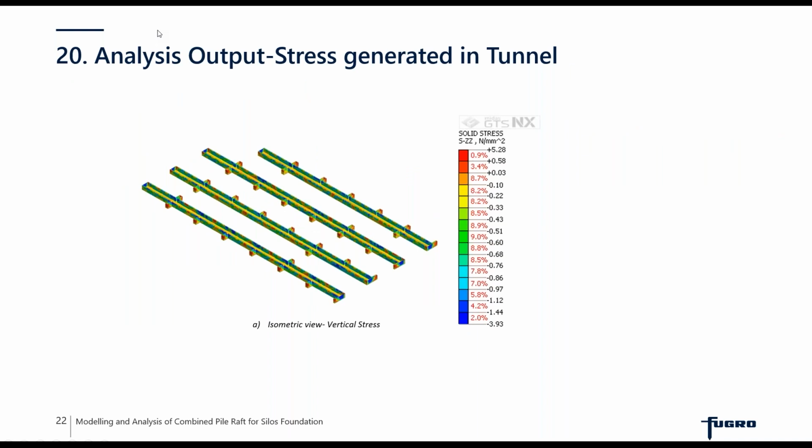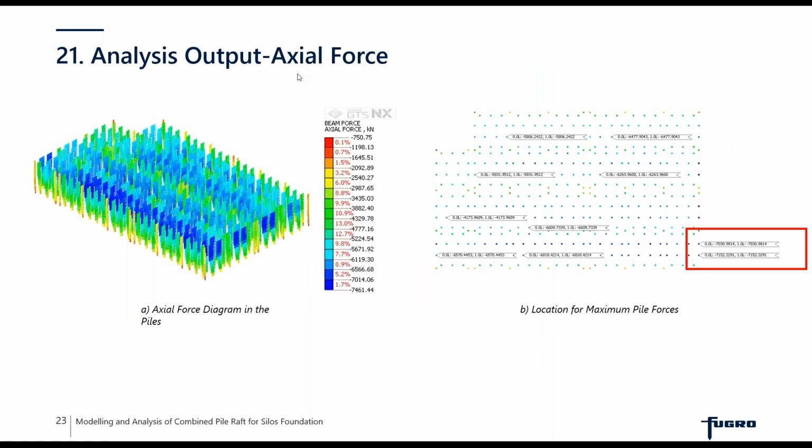Apologies for that. Okay. Now, after that, we also need to check the axial force being generated in the model, and you can see that we are getting the maximum axial force at this corner. For the particular serviceability load criteria which we selected, even the structural analysis was giving the maximum force in the same pile. So you can check the maximum axial force generated against your ultimate capacity and the working load conditions which you have considered in your design.